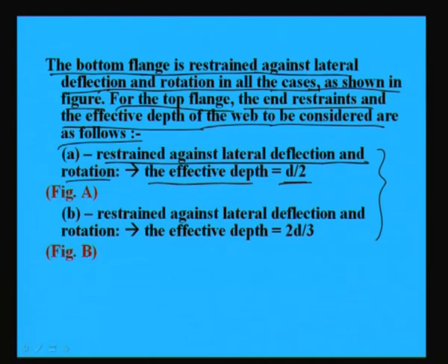Next, when the top flange is restrained against lateral deflection but not fully against rotation, the effective depth will become 2d by 3, right.